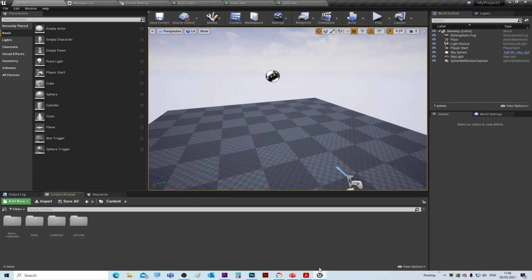Okay, so we're going to create another material now. This is going to be sort of, it could be used for concrete or it could be used for stone. Again, I'm going to use a tile texture that I've already created. I've already created a normal map for it, but this time we're going to look at how you can manipulate the texture tiling coordinates and just tweak some of the settings within the material using the material instance.